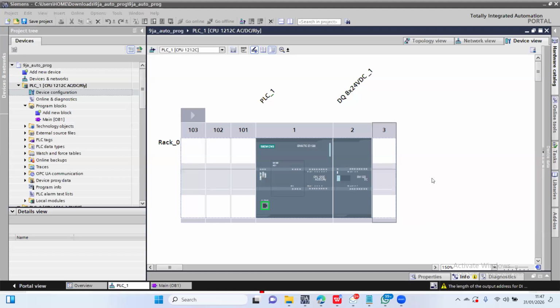So if you are planning to program any PLC that has firmware from version 21 and above, you will use Studio 5000. Anything from version 20 and below, you use RSLogix 5000.